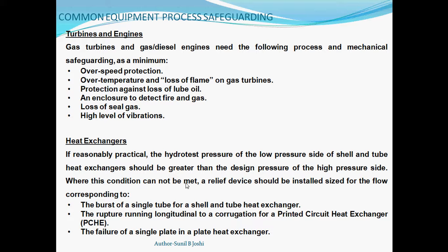So where this condition cannot be met, a relief device should be installed, sized for the flow corresponding to burst of a single tube for a shell and tube heat exchanger, or if it is a printed circuit heat exchanger, then rupture of the running longitudinal to a corrugation has to be considered, or the failure of a single plate in a plate heat exchanger has to be considered.